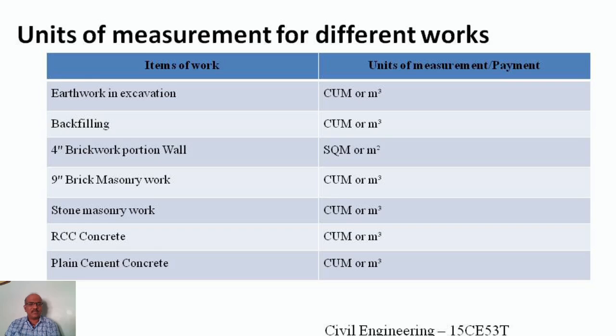The RCC concrete, the concrete masonry, RCC concrete in column, beam, slab, footing concreting are measured in cubic meter. The plain cement concrete in bed concreting or floor concreting or sill concreting is measured in cubic meter.